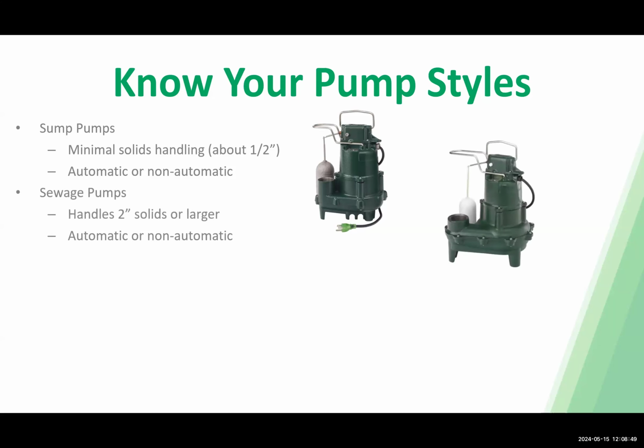Then we have sewage pumps. Sewage pumps handle 2-inch solids or larger. That's typically a requirement by various government agencies to make sure that the solids that you may find in your wastewater are not getting clogged in your system. And these are also automatic or non-automatic.